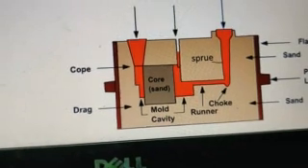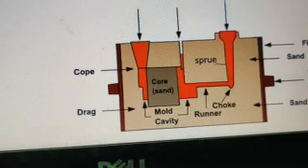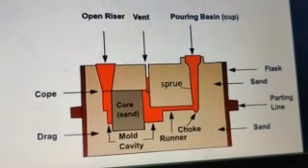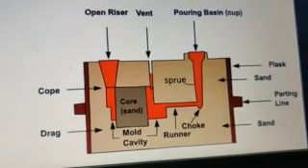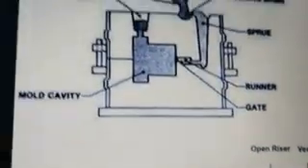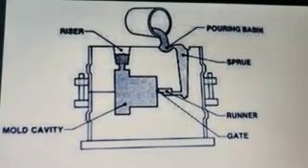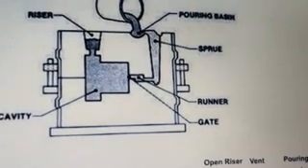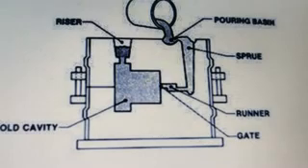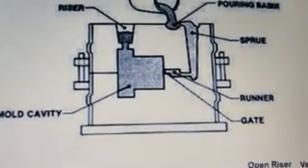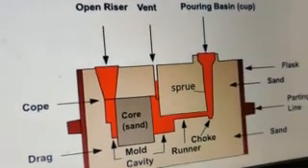The entire operation takes some time, and it is done with very high care, so as to reduce material wastage. Casting is a technique where material wastage can be minimized, since the excess material can always be reused. In the case of sand casting, the sand can be reused by special treatment given to the molding sand. In case it is wet sand molding, you require very little effort to reuse the molding sand.